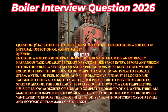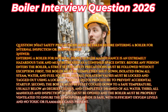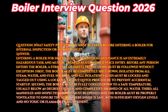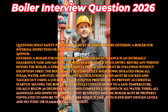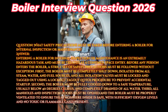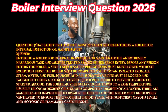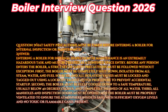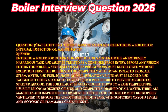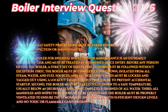First, the boiler must be completely shut down, isolated from all steam, water, and fuel sources, and all isolation valves must be locked and tagged out using a lockout-tagout (LOTO) procedure to prevent accidental startup. Second, the boiler must be fully cooled down to a safe temperature, usually below 40 degrees Celsius, and completely drained of all water. Third, all manholes and inspection doors must be opened and the boiler must be properly ventilated to ensure the atmosphere inside is safe, with sufficient oxygen levels and no toxic or flammable gases present.